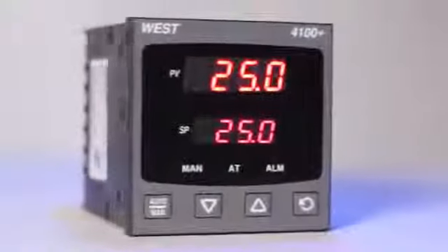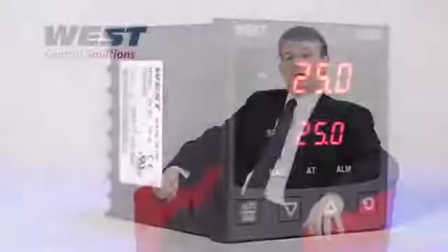In this application, successive banks of heaters are switched on as the process falls further below the set point. Or perhaps you want to stir your process as it's heated to ensure it's well mixed and there is a uniform temperature throughout. However, if your process was viscous and thick when it was cold, attempting to stir it below a certain temperature may cause damage to the stirring mechanism. By connecting the stirrer to a low alarm, you can ensure that the process is at the correct temperature before the stirring begins.